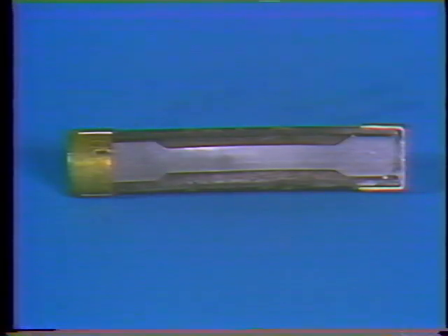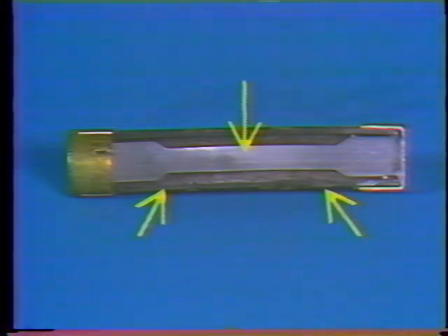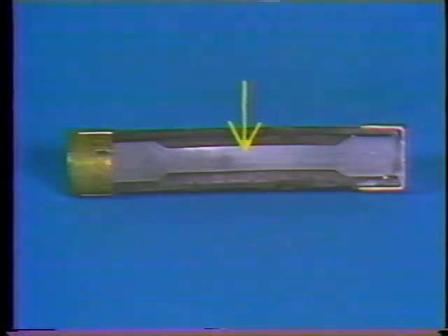Basically, most fuses are pieces of soft metal called fuse elements contained in a housing. The fuse element has a low melting point. It'll melt at much lower temperature than the wires commonly used in electrical circuits. In an excessive current condition, the current flowing through the circuit and through the fuse is higher than normal. The high current causes the fuse element to heat up until it melts and opens the circuit. And that's what actually happens when a fuse blows.